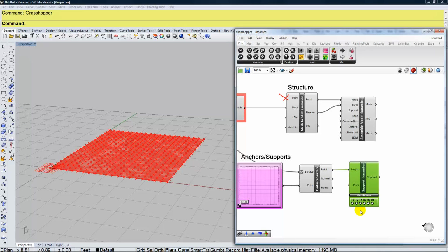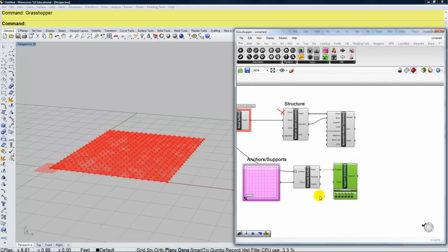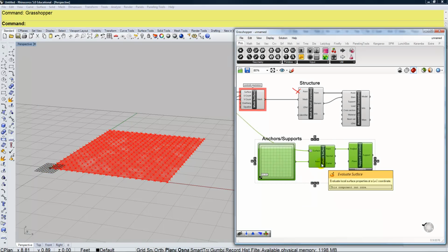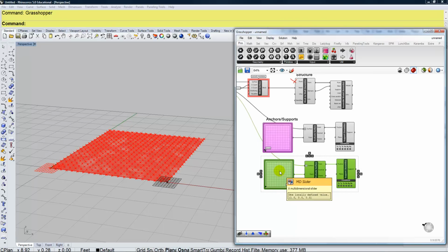And what's really important here to get this mesh form found and moving in 2 directions, I need all these conditions turned on. So I'm going to go ahead and turn those on. That'll make the mesh flexible. Okay, so I have what I need for this one support, but I'm going to go ahead now and select all these and start to drag them down using the Alt key, and I'll position this one in the lower right, so you see that happening in Rhino, and I'll go ahead and make a couple more of these.